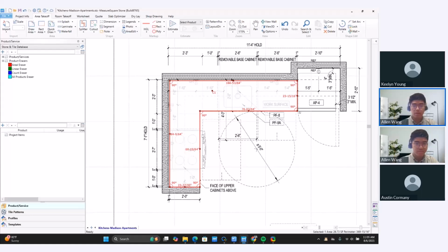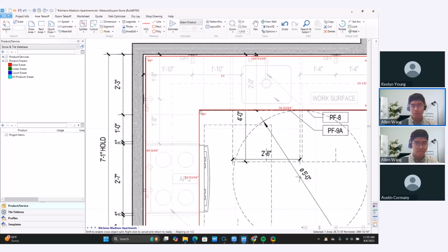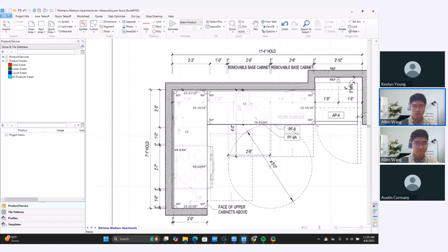So I'll click on the splitter tool up here in the toolbar. In this case, since I want to add a seam that goes vertical from this corner up to the upper edge of the countertop, I'm going to go ahead and click the bottom part of the splitter button. I'm going to select vertical splitter. I'm going to hover over this corner, wait till it snaps. And you can see that there's a preview line that's green going up there. I'm going to click, and you can see that I just dropped a seam here. So it broke out this countertop into two pieces.